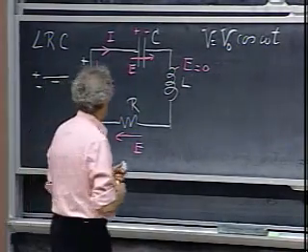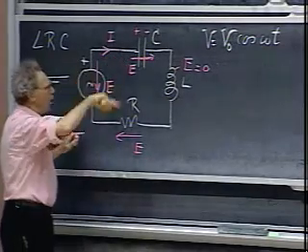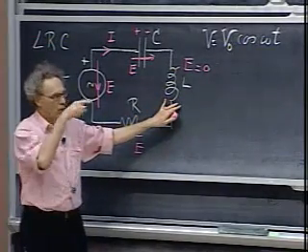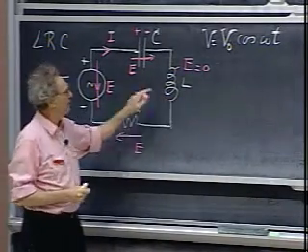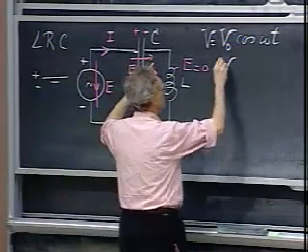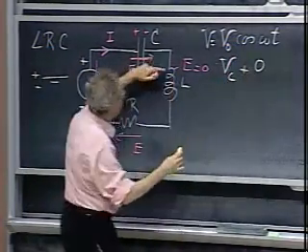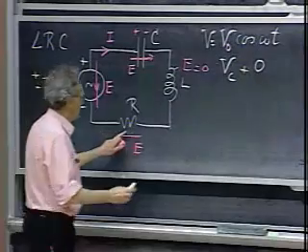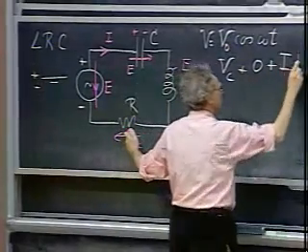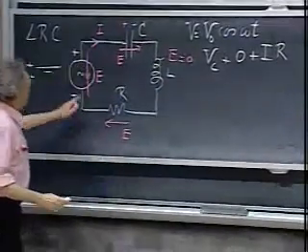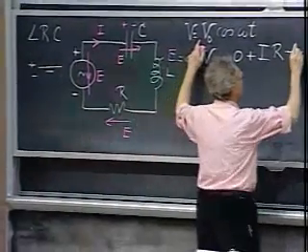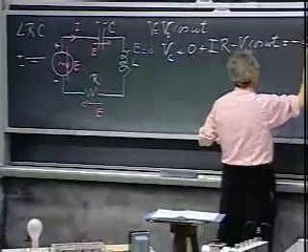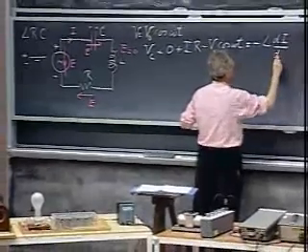So if I set up the differential equation, I start here. I always go in the same direction as I, because only then is the closed loop integral minus L dI/dt. So I go over this capacitor, that is V of C. Then I go through the wire of the self-inductor. There is no electric field, so the integral of E dot dl there is zero. Then I go through the resistor, so I get IR. Then I have my power supply, so I get minus V0 cosine omega t, and that, according to Faraday's law, equals minus L dI/dt.